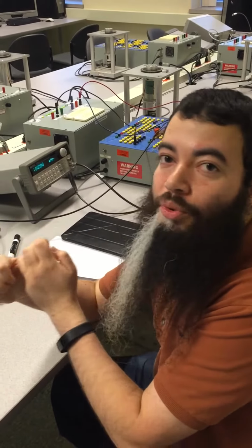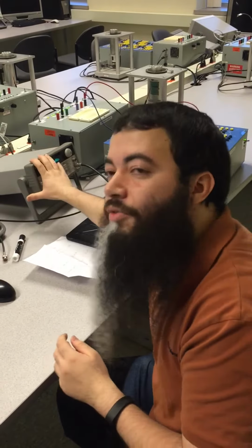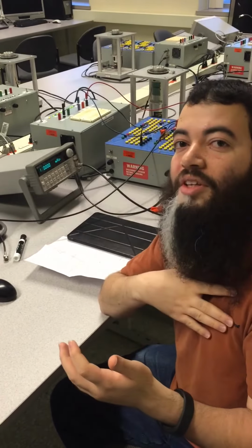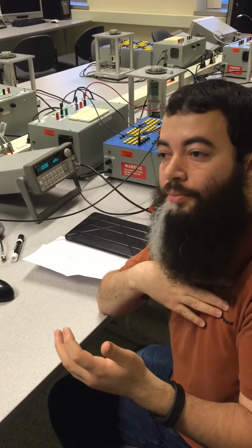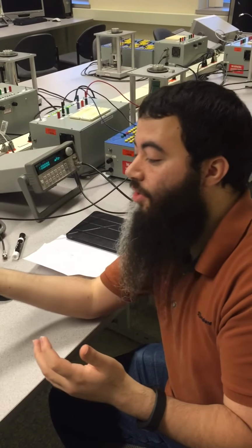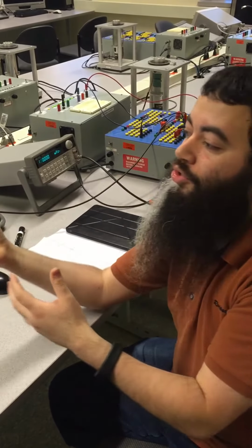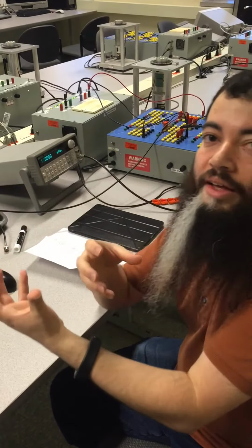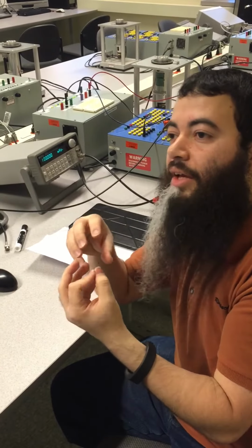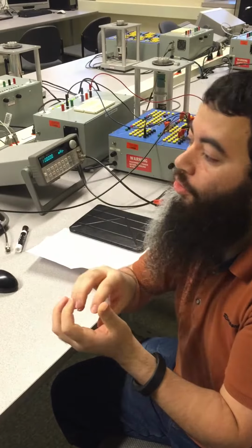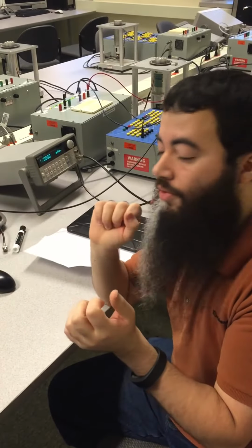Where is my input? Where is my target? This is the signal I generate from the function generator. So my target volt is what I generate from the function generator. I pass it through the circuit, it goes to the motor, and the motor gives me its angle output. According to this angle output, I control the motor. So my control signal goes to the command input of the motor.